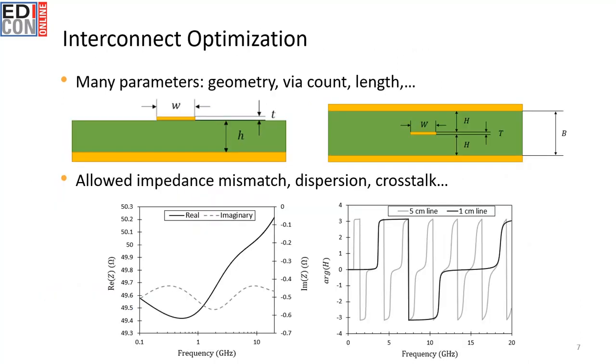So within interconnect optimization, if you can consider the entire bandwidth, you can generate an impedance curve that accounts for dispersion and that accounts for roughness over broad frequency ranges. And so if you include dispersion in the dielectric constant and dispersion in copper roughness, and you do this type of optimization procedure, you don't actually get a straight line at 50 ohms impedance with zero